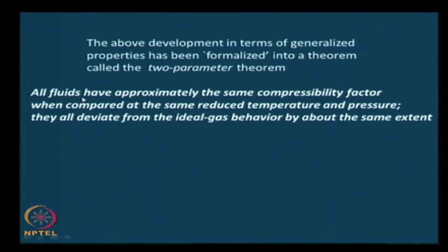Let us read the first sentence again to understand this perspective. All fluids have approximately the same compressibility factor when compared at the same reduced temperature and reduced pressure, and from this, just by using the reduced temperature and reduced pressure appropriately and using the compressibility factor, we have information about a large variety of gases. That is the advantage here.